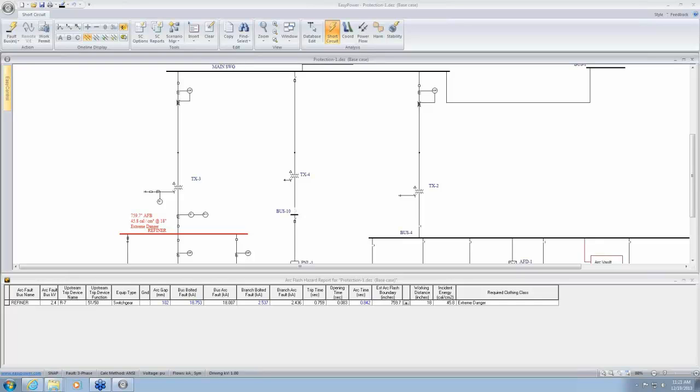Next question, did you say that the arc fault is considered 30 to 40% of voltage fault value? Yes, I've seen some people doing that. I would recommend not doing that because the standard says, use the arc current equation. But again, that option is there for those who really have their own information and have done their own testing. Otherwise, avoid using that. Yes, I've seen people use something like 38% to 40%.